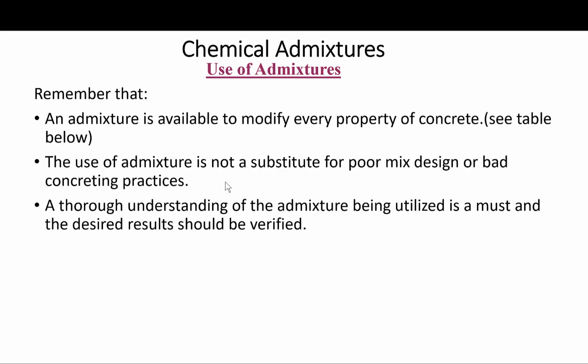Okay, an admixture should be used to improve concrete construction, be it handling or consolidation of fresh concrete, or in the performance of the hardened concrete, or maybe in the cost of construction. It should be emphasized, though, and keep that in mind, that an admixture is not a substitute for poor mixing or sloppy concrete practices. Okay? And the potential user should first ensure that the desired result cannot be attained by improvements in these areas.